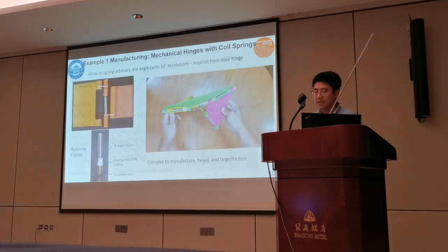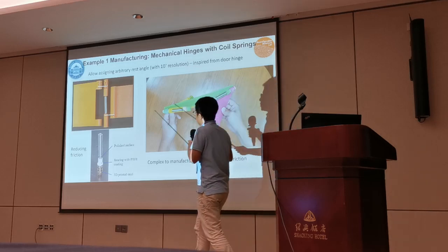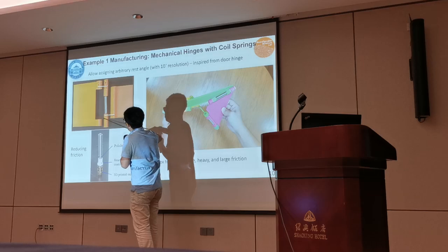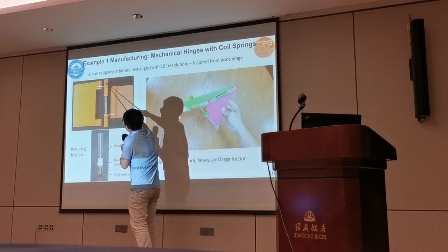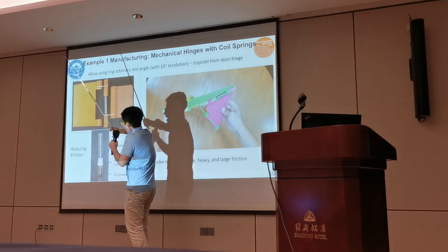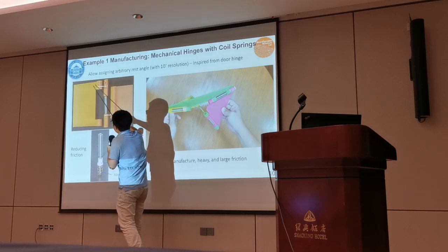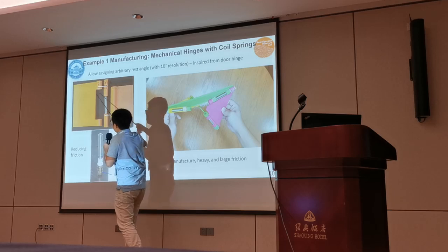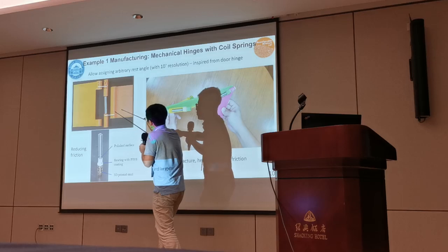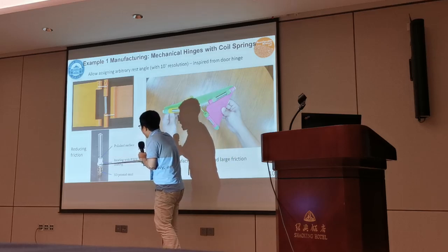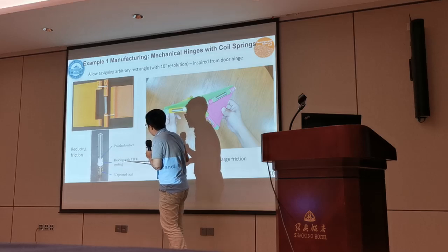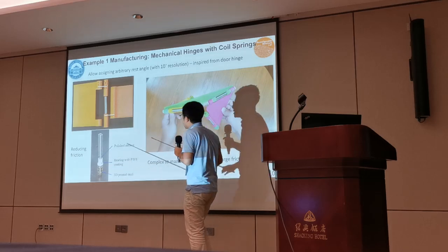The difficulty is manufacturing. I kind of learned from the door hinge, right? I have torsional springs, and you can notice I have a lot of holes. I need to turn it to the right degree, and then the right holes will match each other, and I insert a pin in it to keep the right rest angle. I also made some efforts in reducing the friction with this polished surface and with the bearings and so on. I did a lot of stuff.